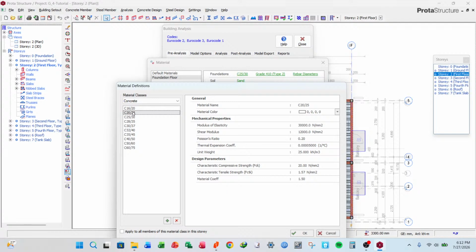In most cases, when the soil is contaminated with sulfates, when your soils have high percentages of salts like sulfates, chlorides, these react with the cement in the concrete and compromise its integrity. So you'll have to use a stronger grade of concrete.